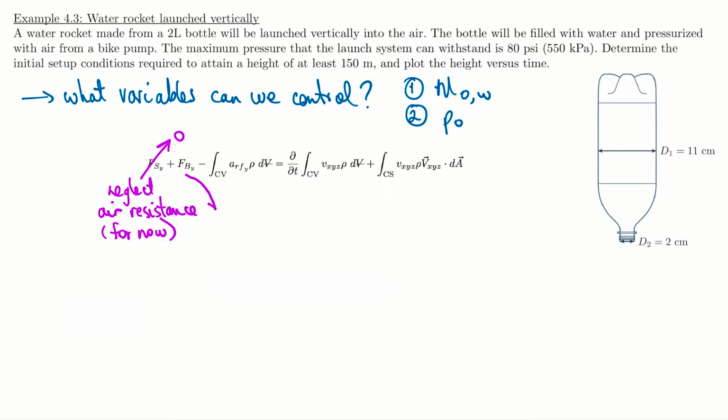Now we've got the body force term. We're going to solve different equations, so I'm going to give each equation its own color so we can be clear about which one we're solving at which time. And we've seen that this is mass times acceleration due to gravity. CV's control volume. Negative g m_CV. I'll actually explicitly draw the coordinate system on this. Gravity's acting downwards. We've drawn y as positive upwards. So we'll write that as negative g m_CV.